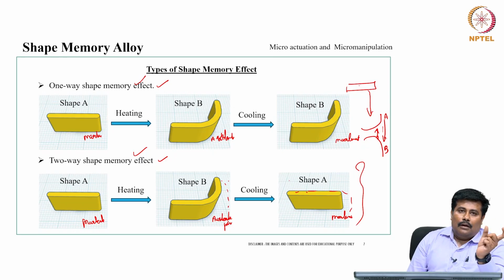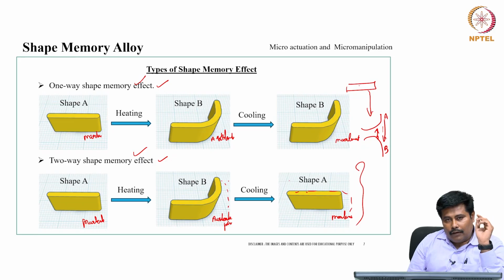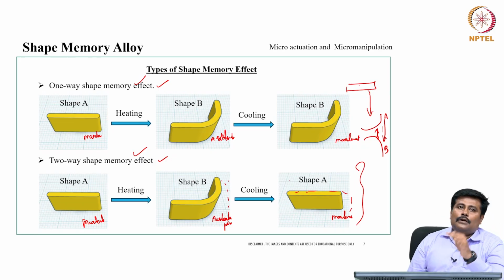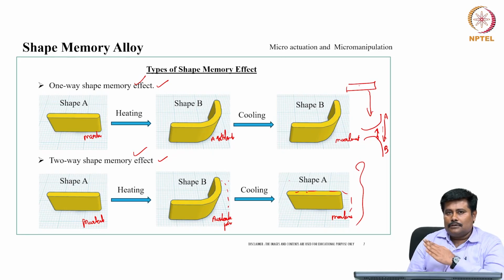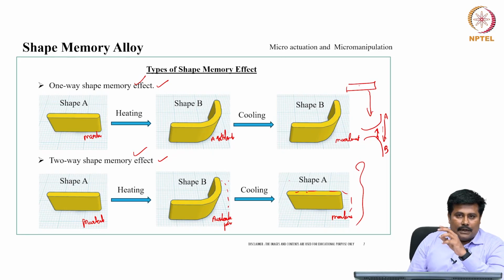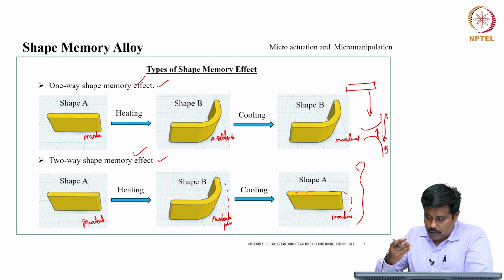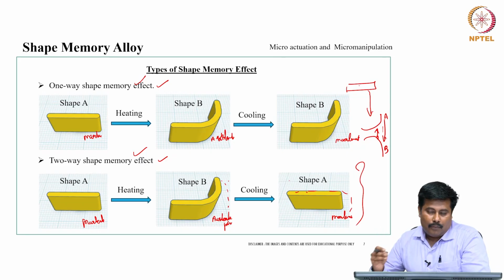If we need to program it appropriately, we may need to have a manipulation in the memory of the material. For that, certain methodologies are followed. Since it works on the austenite to martensite transformation, a die can be prepared and appropriately deployed in hot and cold conditions, and then we can train the material. Shape setting can be evolved out of it.